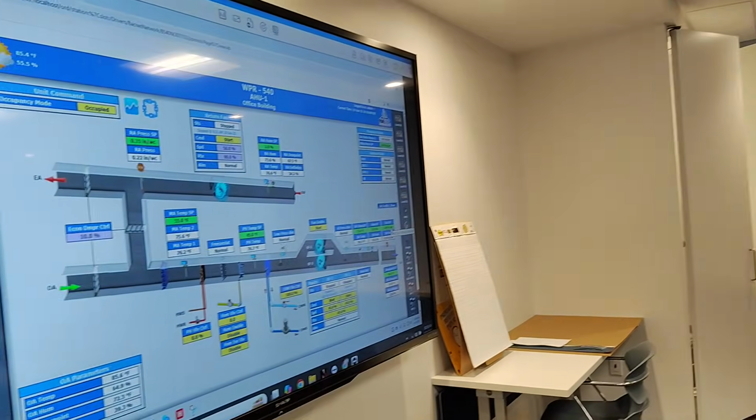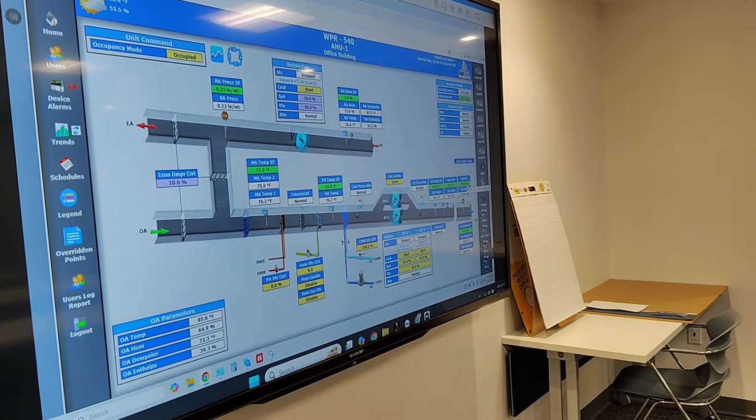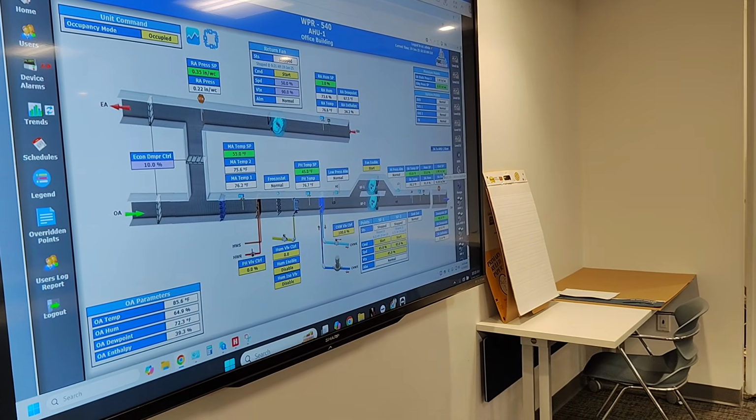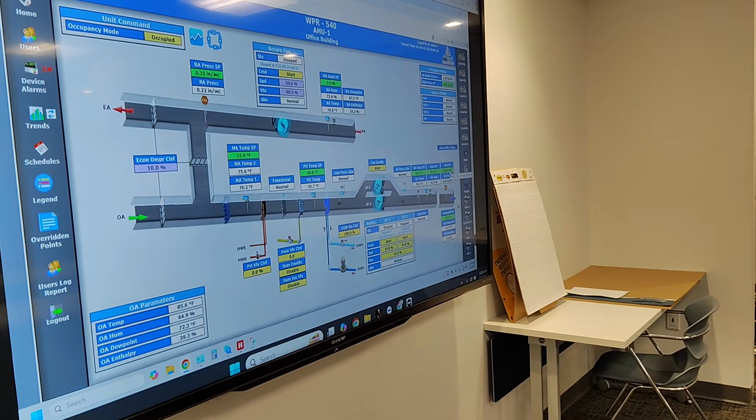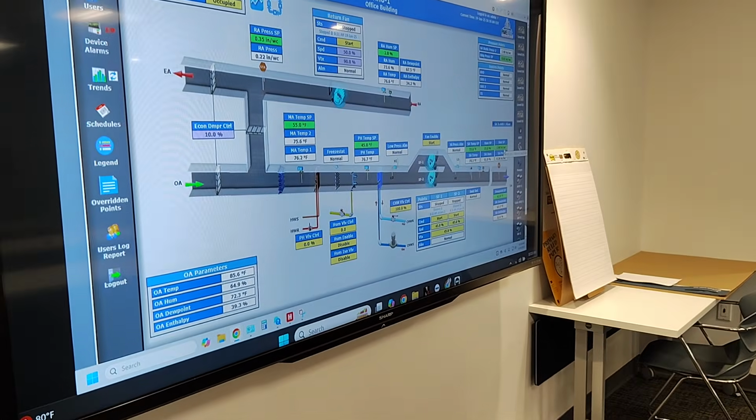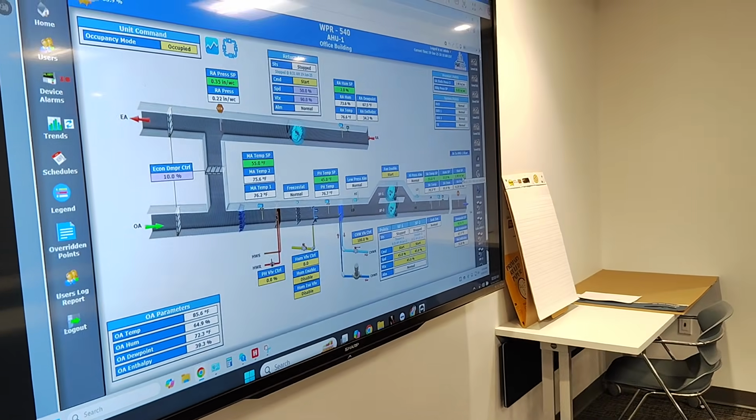Does it actually say the RPM? Does it say the hertz? No. That shows you percentage. Percentage is percentage of 60 hertz, but really it's percentage of span. Because that thing has a minimum hertz of, I think, like 10 or 8, it's not going to be 0 to 60, it's going to be like 5 to 60, right? So when you get to 50%, you're actually more like 35 hertz on the VFD.